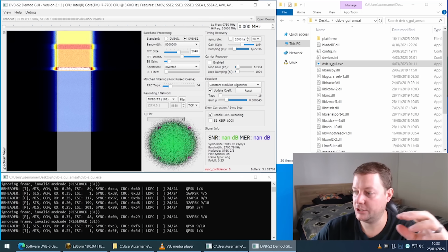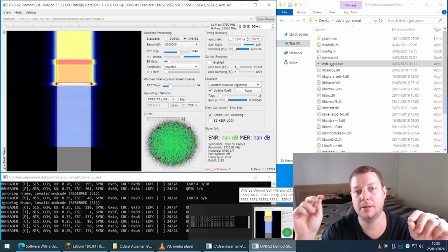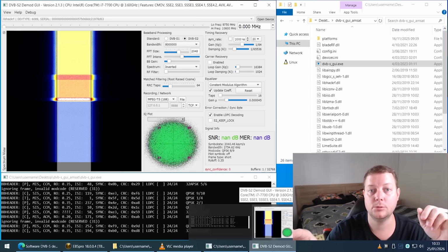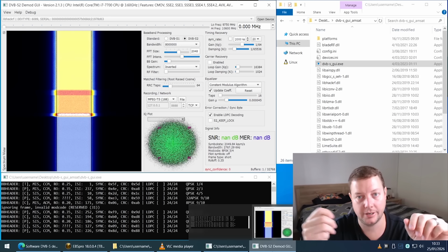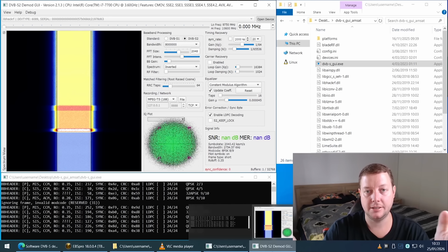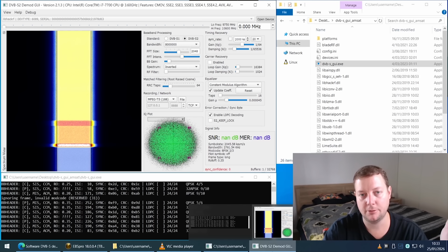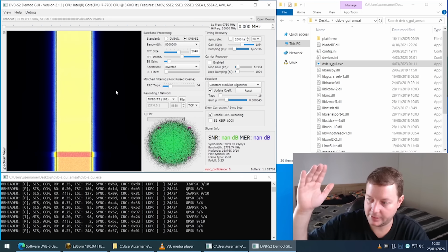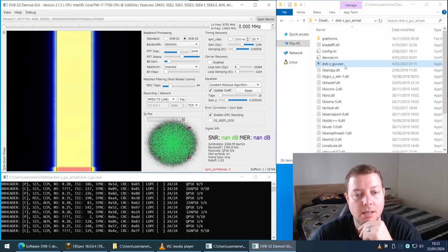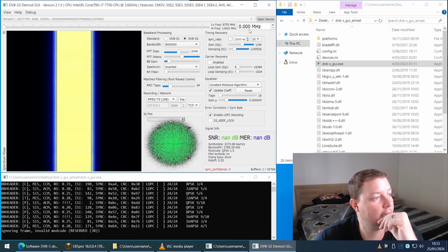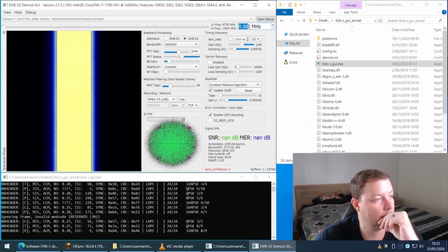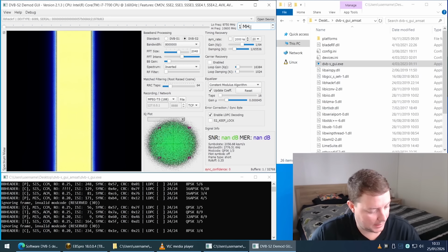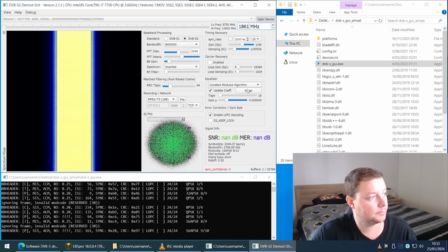So you don't need too much gain, guys, because the LNB is actually sending quite a strong signal indoors. So you really do not need a lot of gain. And if you exceed the input voltage of your SDR's RF input, you're going to have a bad time. So don't do that. Just keep the gain levels very low for me, please, guys. Okay, I'm going to change the VFO now to 1861.